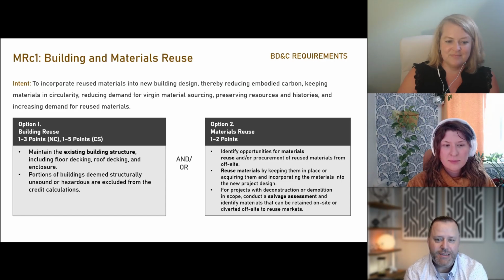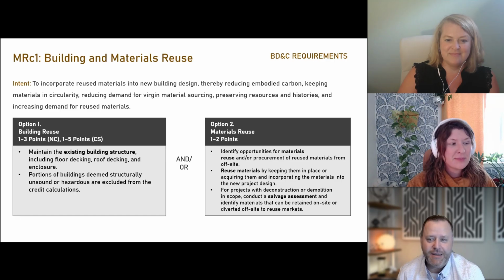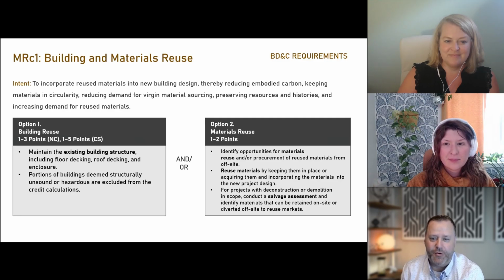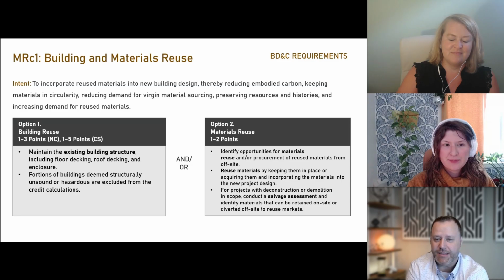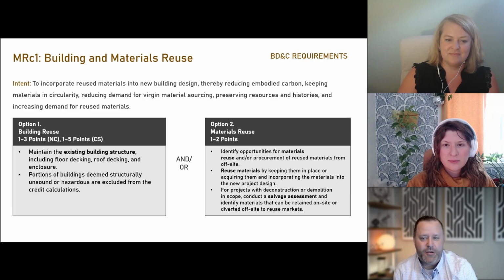There's a few strategies in LEED that are kind of like multipliers. You do a great strategy and it gives you lots of points in the rating system. Things like a green roof or procuring renewable energy. You'll get points for that, and it also helps with other places in the rating system. Like green roof helps you with rainwater reduction or capture reduction. It helps you with insulating the building, for example, as well as providing habitat and space. And things like renewables help you with your energy code performance and your carbon assessment and your carbon credits, as well as things like the renewable energy credits.